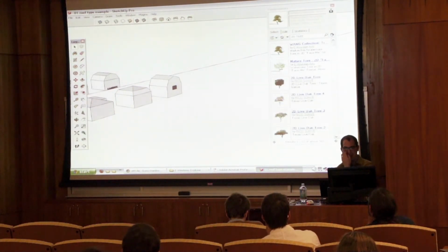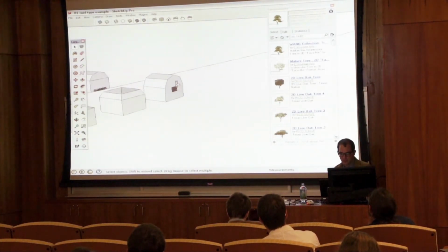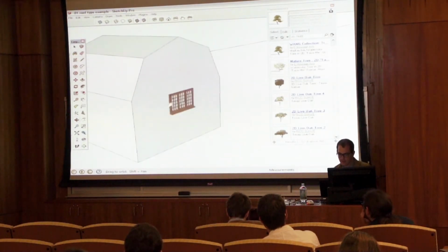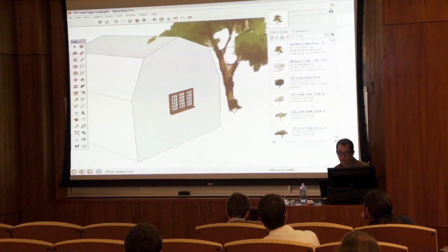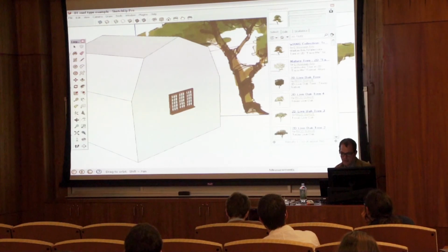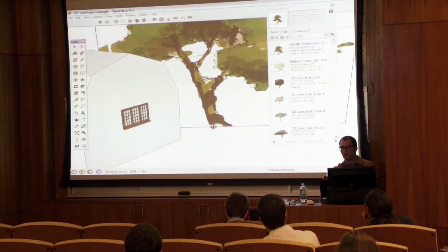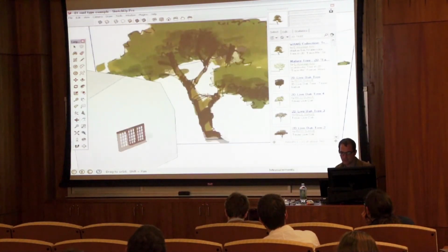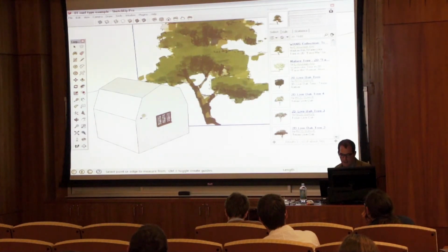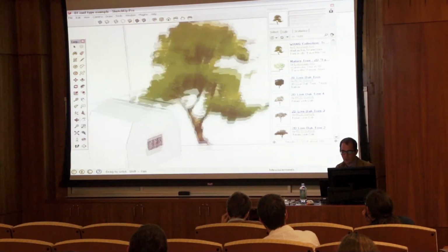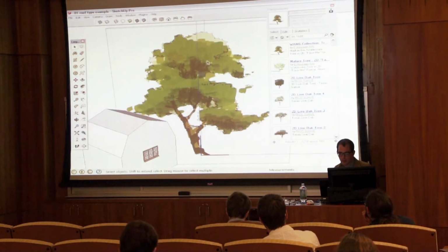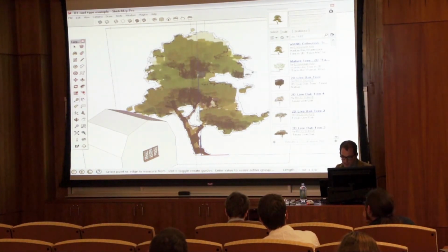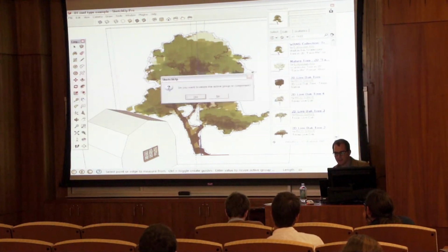These items like the windows that you're bringing in, can you scale those and stretch them and make them larger and smaller? Yeah, so one challenge with components from 3D Warehouse is they're done by other providers. So in some cases, they come in too big or too small. The advantage of that, though, is any group or component you can auto size or scale. So this tree, for example, comes in at whatever size it is. Let's say we want the height of that tree to be 30 feet. What you can do is take the Select tool and double click so that you're inside that component. You can then take the Tape Measure and measure the height. Right now it's saying it's about 50 feet. And I can type in a new value. So I'll type in 30 foot sign and press enter.